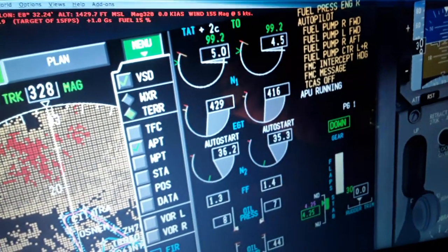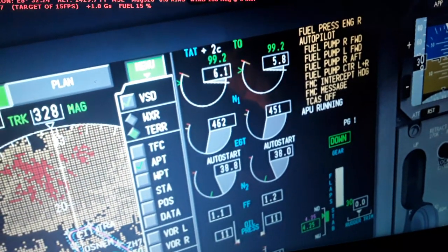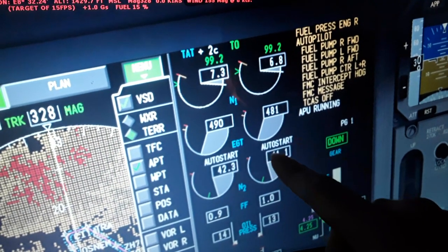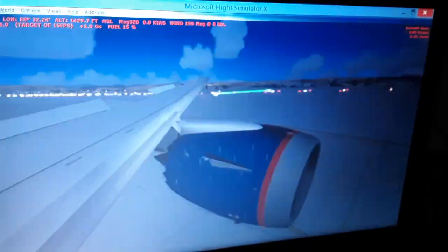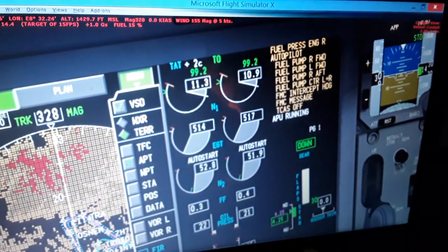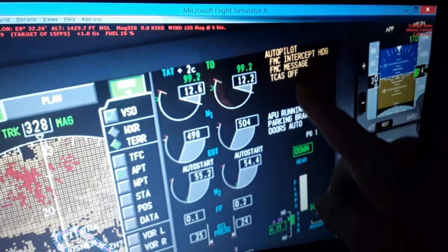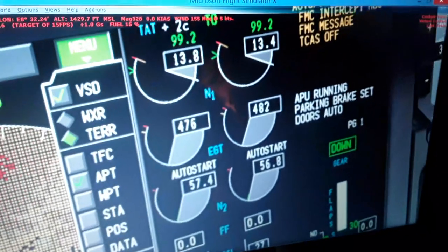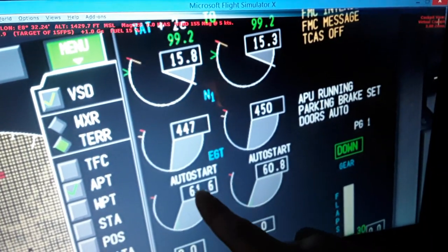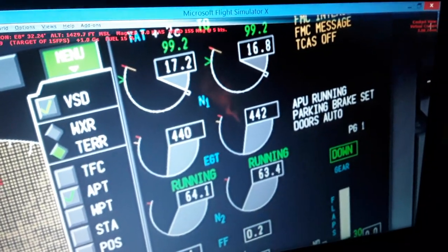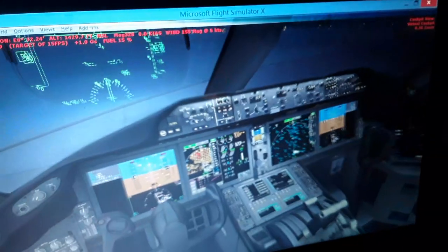So we are at 34, 35. We need one more minute to go for flight. So we have 40%. You can see the messages are going off, and we have running engines over here, both with green color. Here we are, not running. So we use flaps for takeoff over here, parking brakes off, advance the thrust levers over here and going for the runway.